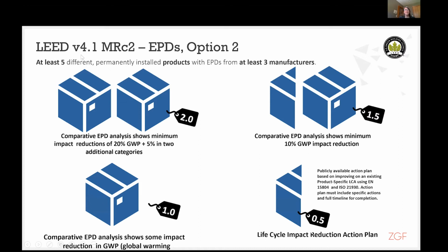I did miss one point that I really want to make sure you all know. When you're talking about really any of the materials credits, you're going to want to do a LEED version 4.1 credit substitution. All of the materials related credits got easier under LEED version 4.1. If you're doing straight LEED version 4, you're going to be in trouble on the materials credits. You're not going to be able to achieve as much as you want to, LEED point-wise,